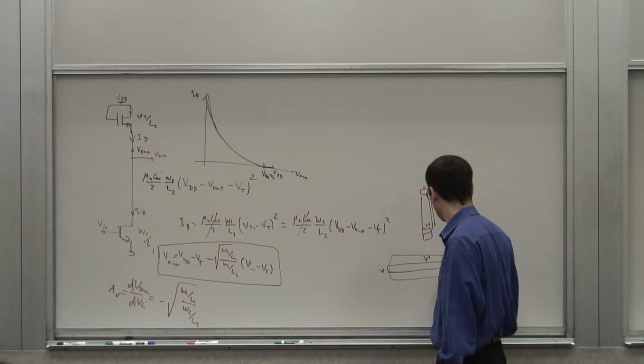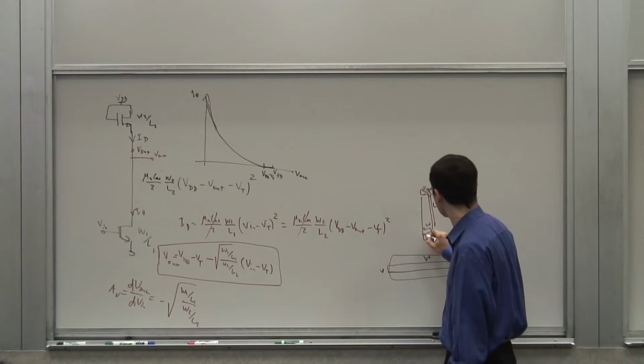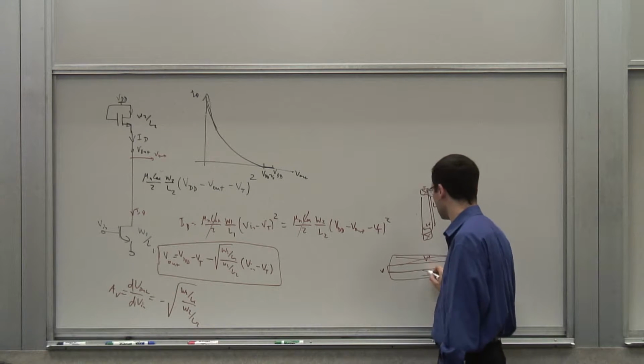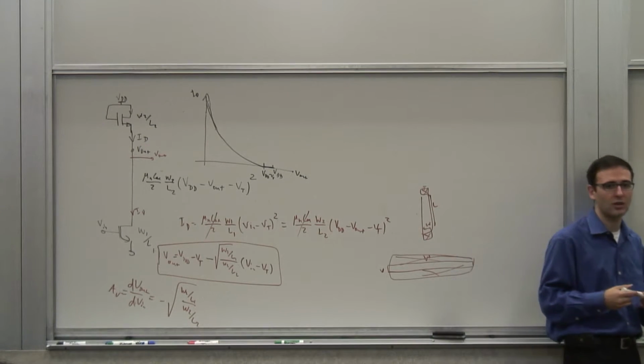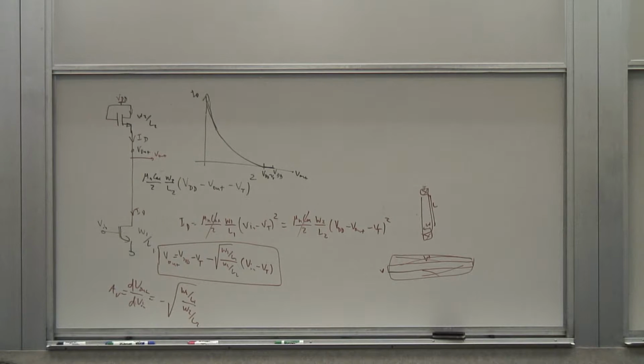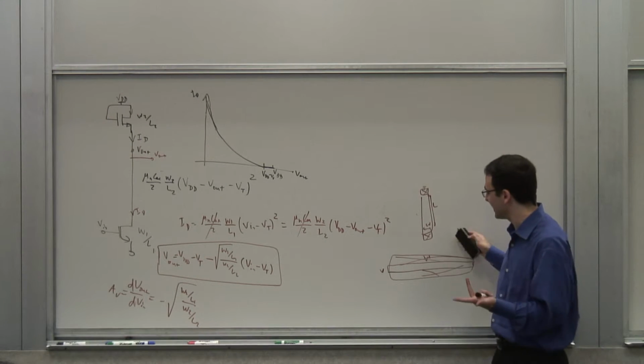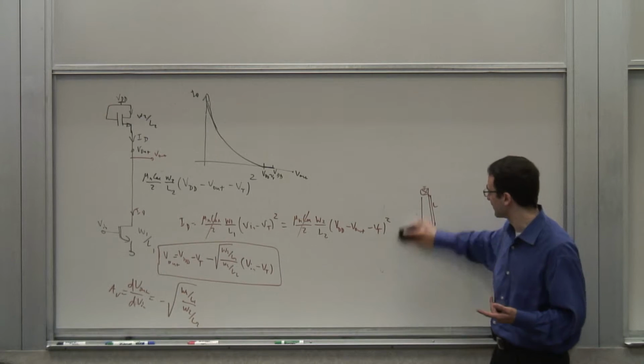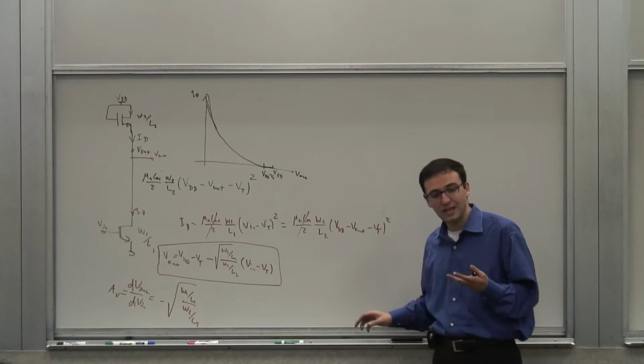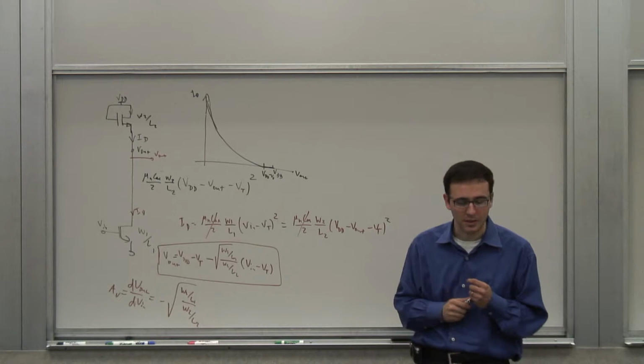So this is the one transistor, this is the other transistor, this is the drain and source, that drain and source. You can see it will start looking awkward even for reasonable people. Of course, you can break it up into multiple transistors and put them in parallel. But still, you have this kind of ratio problem. So your gain is low, as you can see.